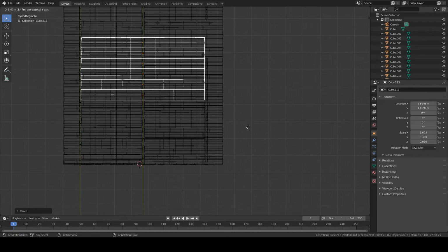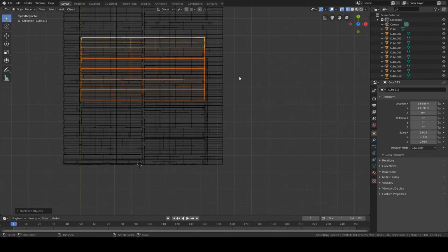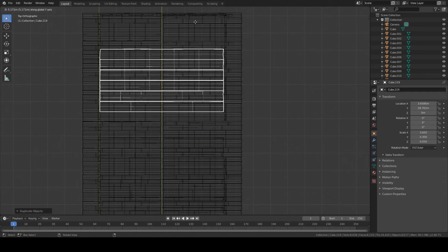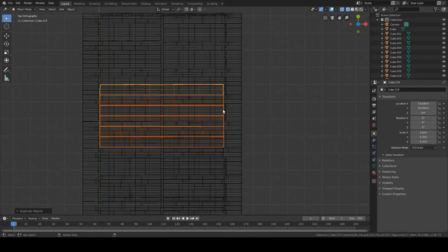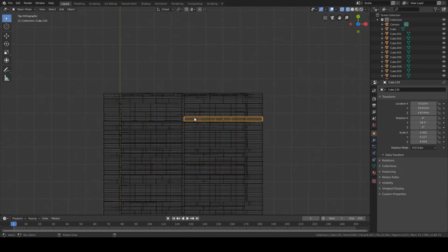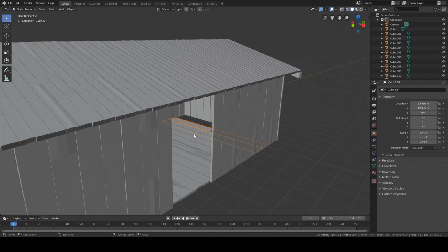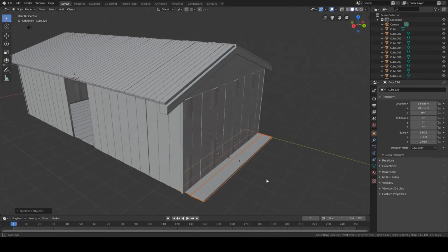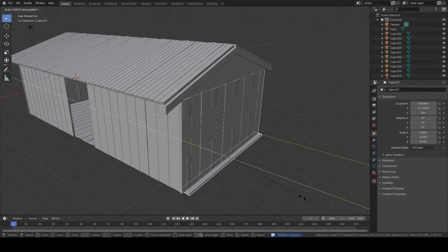And then just Shift D to duplicate these on top of the other ones. Which it's not the easiest to see in wireframe mode, but it's not too bad. You might have to squint your eyes. Yeah. And duplicate it one more time. And then maybe just grab these 3. We're going to Shift D and then just move it down on the y-axis. And we'll delete this one. We'll just scale this down on the Y to make it fit inside.